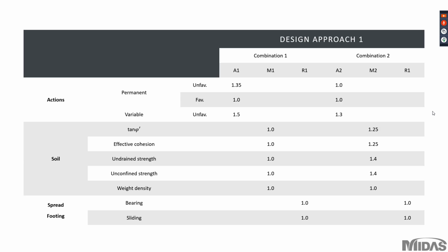And the partial factor values from actions will be multiplied by the original load, and the soil strength will be decreased when you apply the partial factor compared with the original materials. So I guess you will get a more conservative result compared with the original result, right?